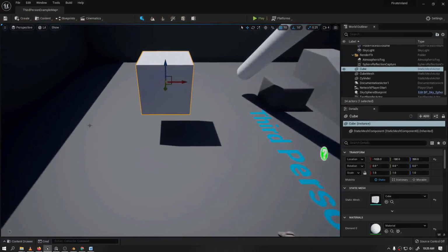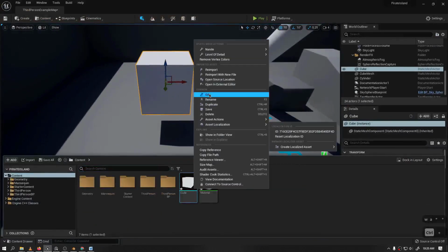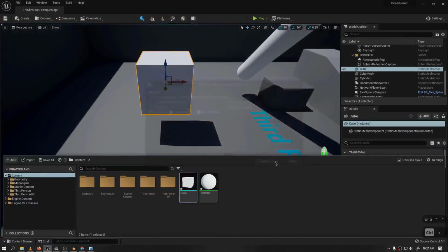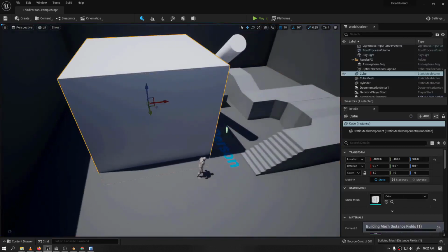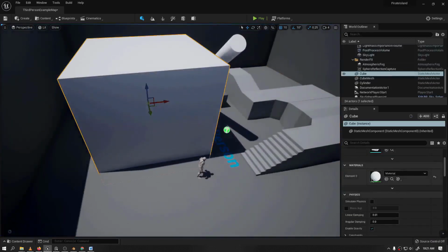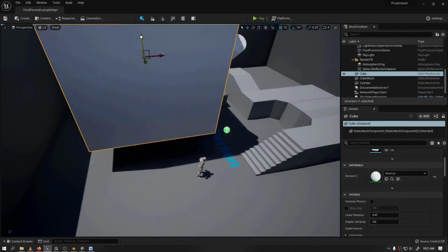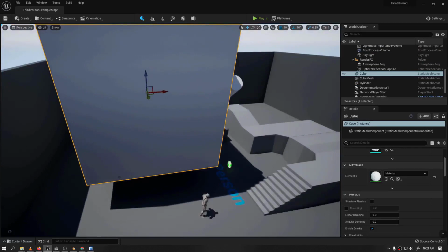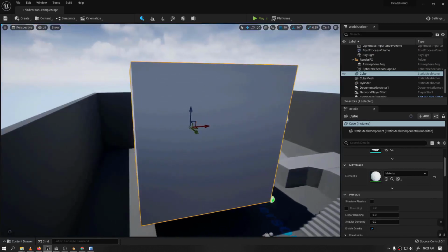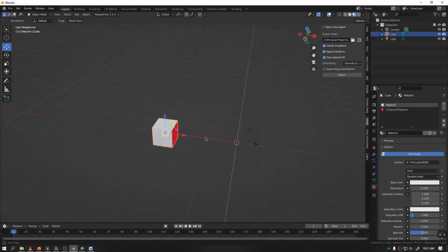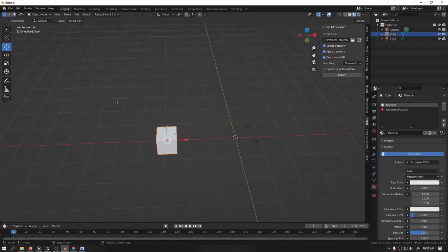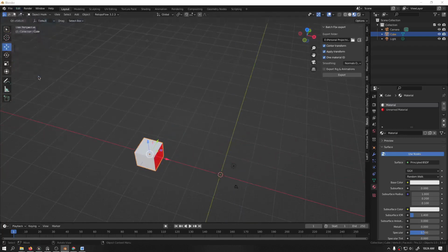As you saw, this object had a couple of materials inside Unreal, inside Blender, and when we import it with these conditions in Blender, you see the material has just been reset to one material. So if your object has multiple materials, you want to disable that. And this resizing you see has happened here is because we have resized the object in Blender, and that doesn't matter really. So another add-on that you can install, of course, it's in Blender by default.